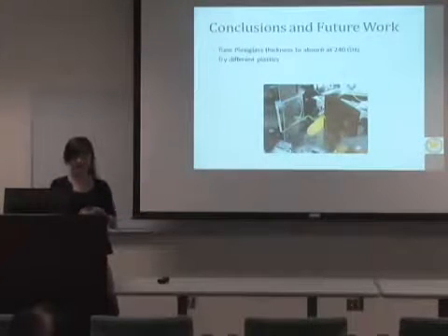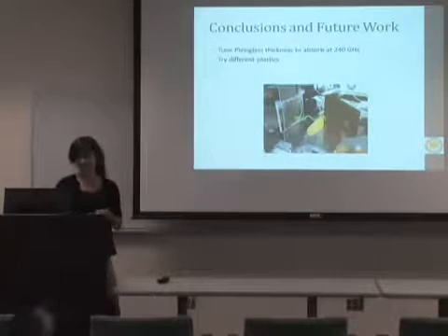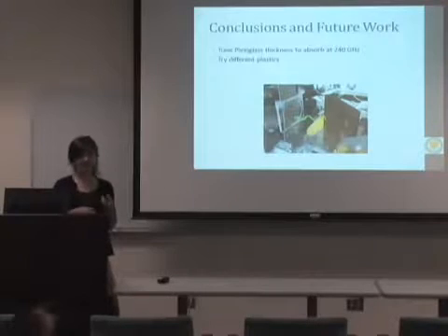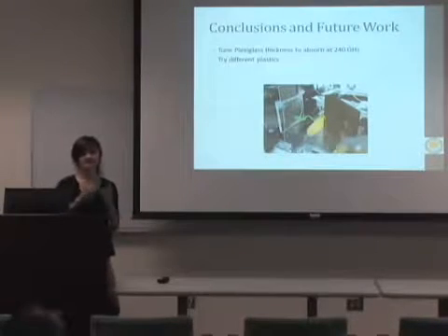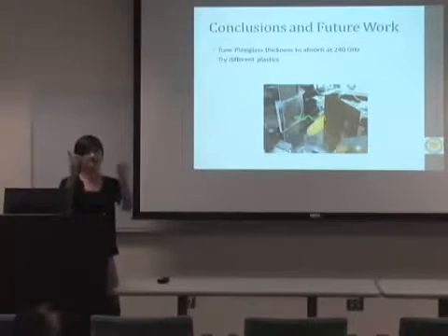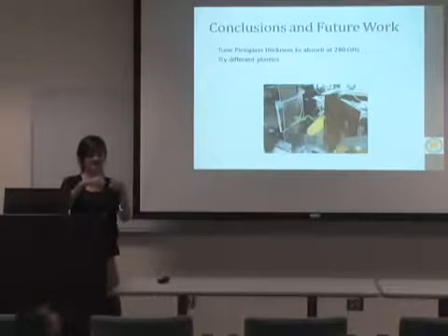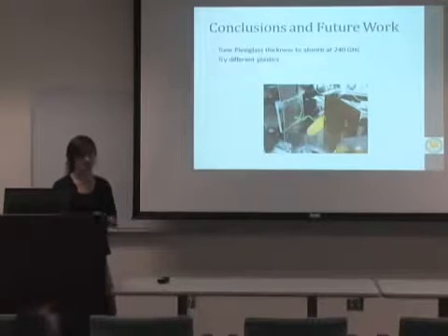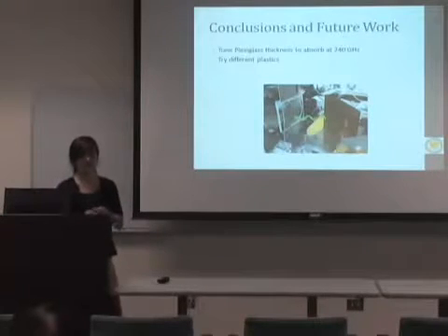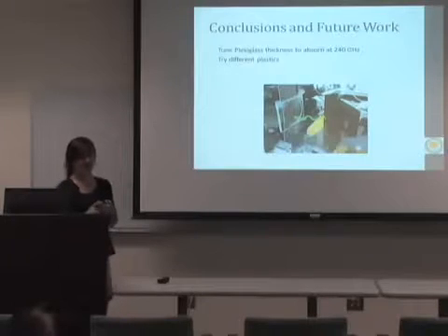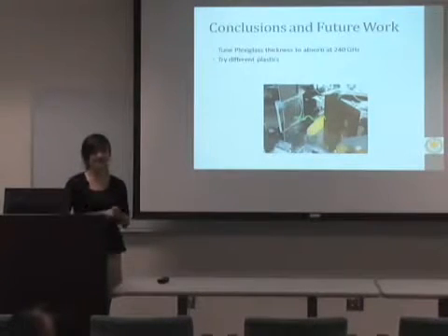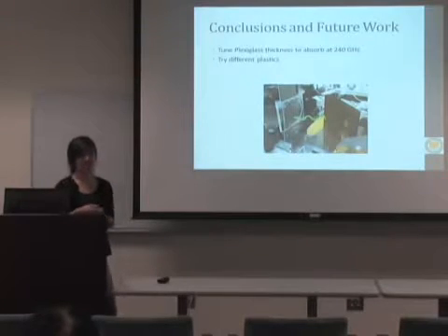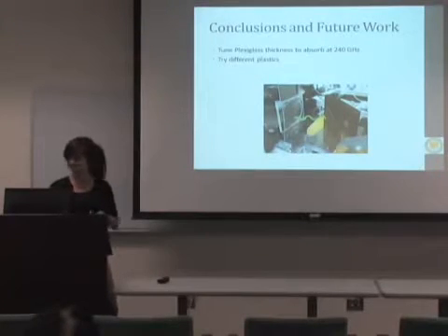So in order to continue on with making new absorbers, I'm going to tune the plexiglass thickness so that it absorbs at 240 gigahertz, so that big peak moves over to 240 gigahertz. And then also try different plastics that are similar in index of refraction to mylar and plexiglass to see if we can get a greater reflection or greater absorbance closer to the cone that was 1 in 100,000.